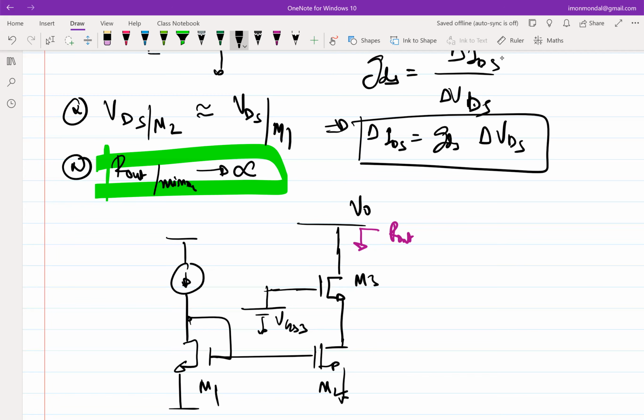Okay, so this is good, right? If I am not satisfied, I can put another cascode on top, and it will go down by another factor of the intrinsic gain of that transistor, right? So I can keep playing the game as long as I'm okay with the signal swing, because ultimately, the moment you put transistors on top of each other, you lose signal swing. Okay, fine. So it looks like we have a handle on how to tackle the second point: R out tends to infinity or very high, with respect to the load that it is driving.